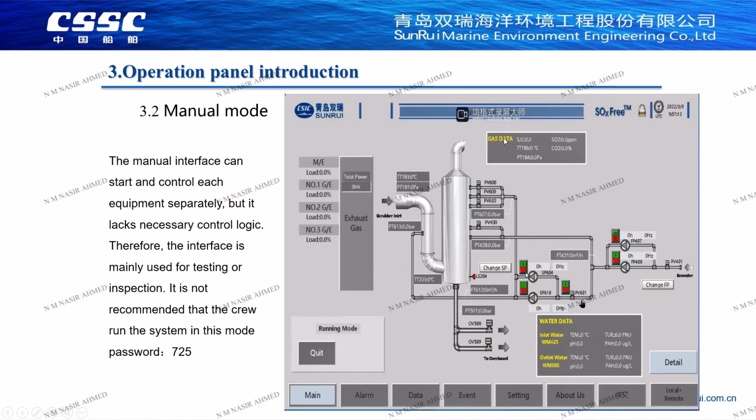Start the device you want to start in the manual screen, such as spray pumps and pre-spray pumps. Of course, before we start, you need to enter the frequency of the pump, and then these valves of seawater can also be opened and closed manually.